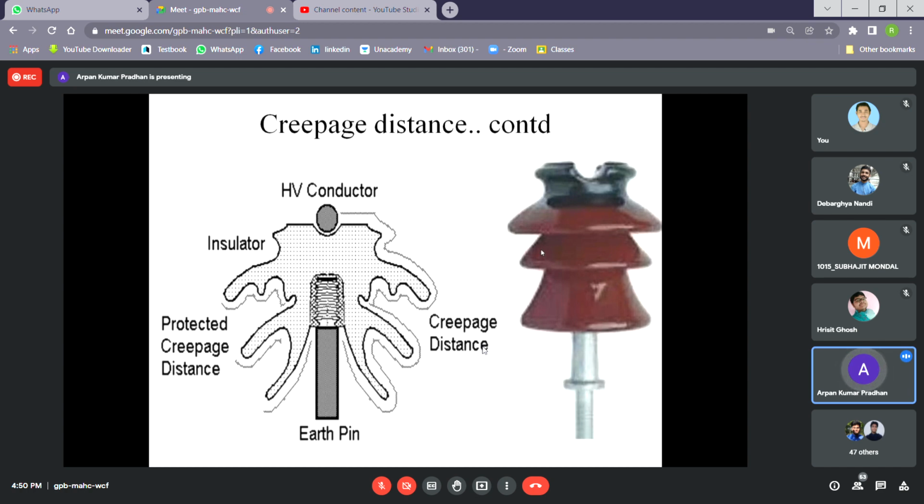So you have to be very cautious while monitoring the insulators. If the flashover occurs repeatedly, a permanent sign, or tracking sign, can be seen on the insulator surface, and that tracking path will help to break down the air at low voltage. So that may harm the insulators.